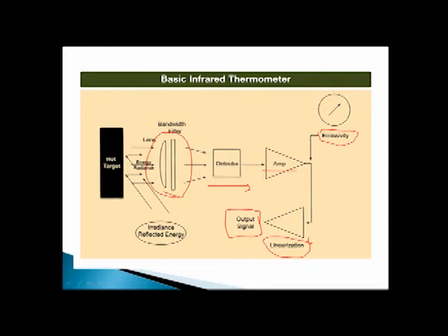Electronics can be incorporated to convert the analog output to digital signals that can be transmitted at high speeds, allowing for extremely fast data acquisition rates. Ambient temperature compensation electronics ensure that temperature variations inside the infrared thermometer do not impact its output. Some applications with extremely hot operating environments can require water jacket cooling at the infrared sensor.